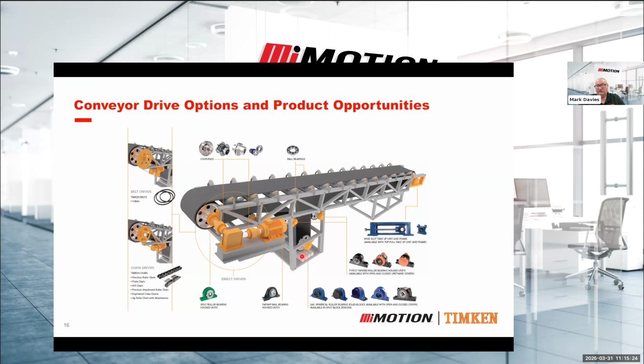So you have a large concrete or metal mass sitting underneath on a trolley system, so it can actually stretch the conveyor belt. And the stretching of the conveyor belt gives the traction around the pulleys that actually allows it to drive on the head pulley. So this is rubber lagged or ceramic lagged, a lagging being the outside cover of the pulley. So it's rubber on rubber or rubber on ceramic, which gives a very good positive drive to the conveyor belt.